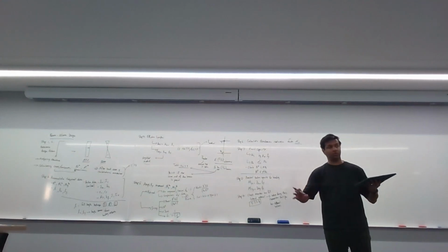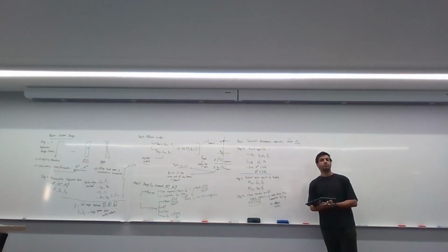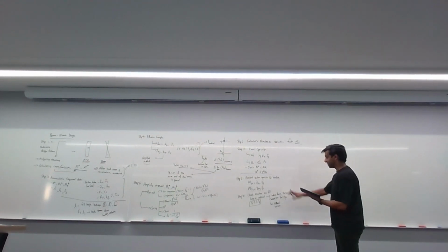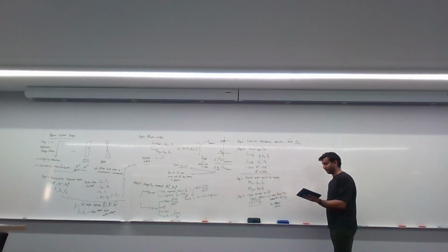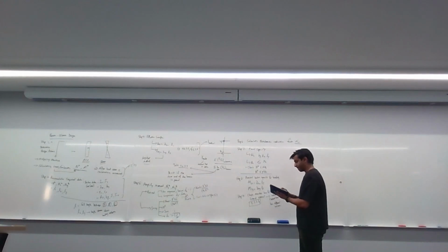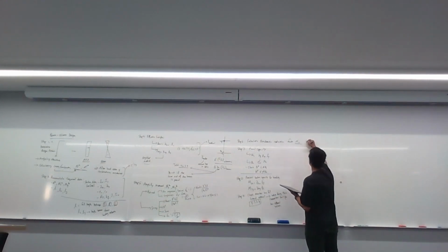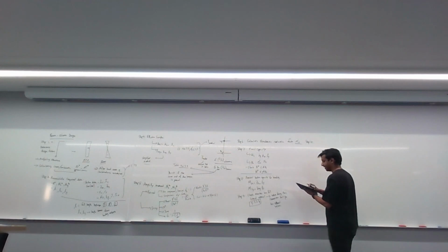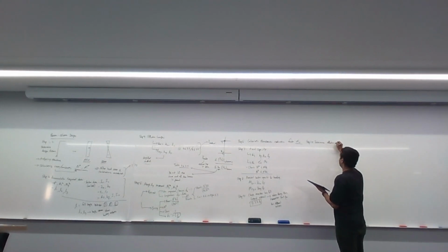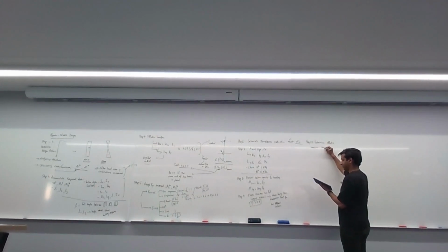All of this is in the code. So when you're doing this check, please remember to use the correct and appropriate beta M value. That's step 9, checking for full lateral restraint. If you don't have it, then you go on to step 10, which is to determine the effective member length for bending.